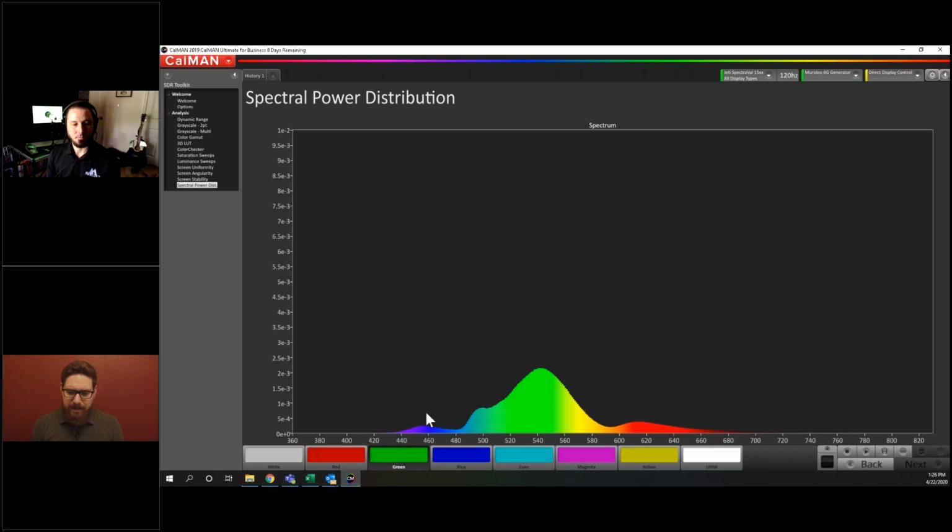Because instead of treating the display as, hey, the spectrum of red, green, and blue equals white, it's treating it as there's 3 separate subgamuts, because the LG OLED panels have 4 subpixels. They can only light up 3 at a time, and one has to be white. So only 2 of the colored subpixels are on at a time. So they have 3 different combinations of those, and we have a different matrix to correct each one of those individually.